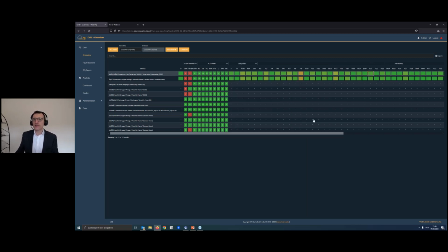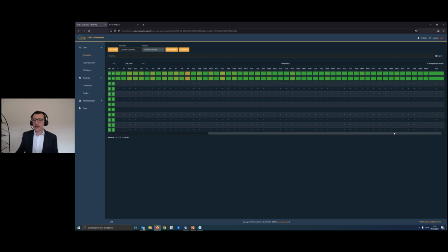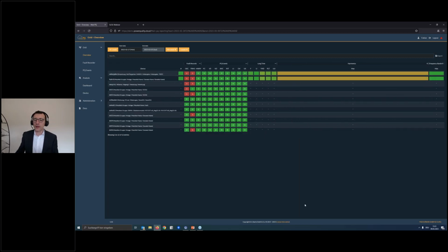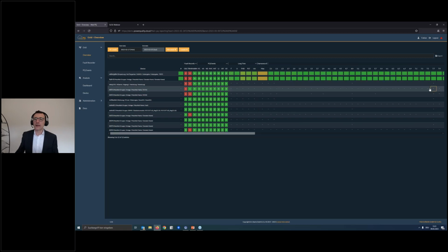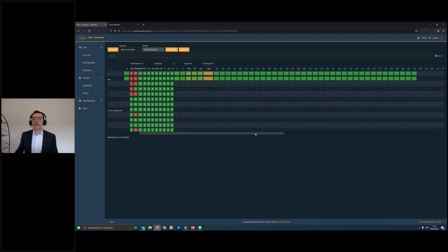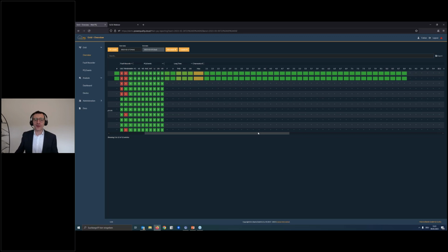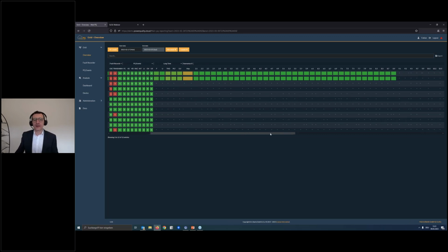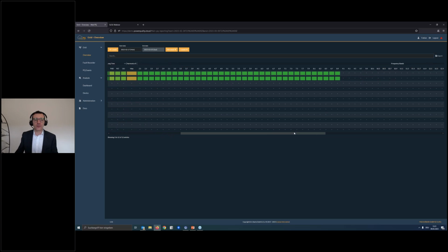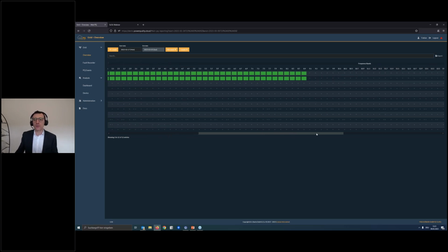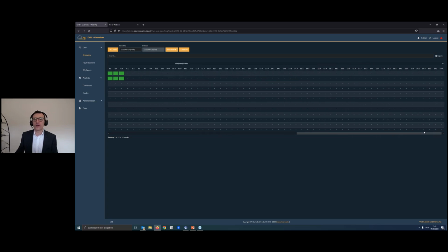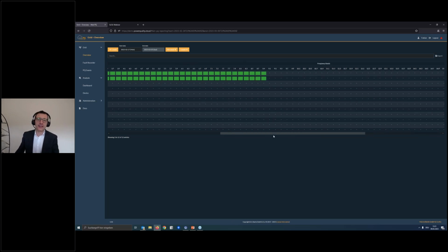All the harmonics until the 50th harmonic can be displayed, and a very new and future-oriented functionality is the frequency bands 2 to 9 kilohertz, and therefore I can also give you an outlook. We will in the future also be able to measure continuously with our fixed installed devices up to 20 kilohertz. We have already prepared that here, as can be seen.